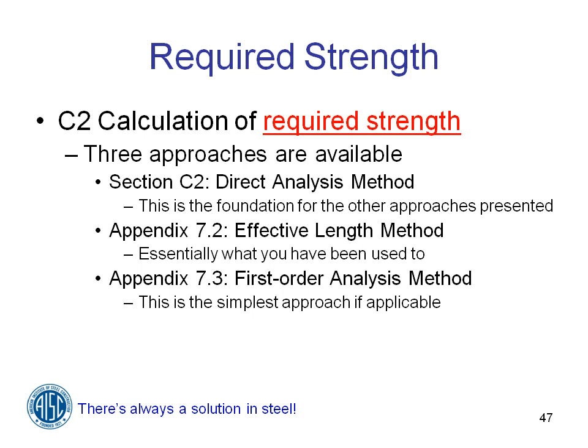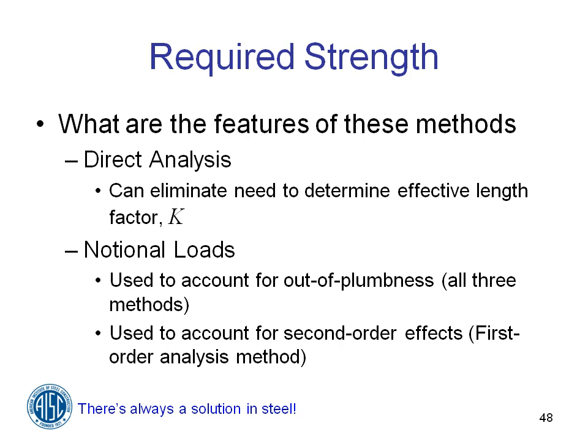And what you will find if you go back and check the structures that you have designed, I would expect that most of your structures will meet the requirements to be done by the effective length method, which means the way you've been doing it in the past. And then we have the first order analysis method, and this is a new method with the 2005 specification, and it is really the simplest if it's applicable to the structure that you're working with.